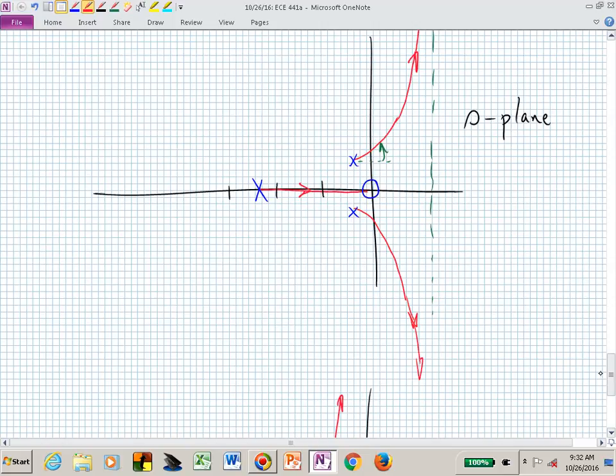So now the k, so if k is 0, where am I? If k is equal to 0, where am I in this top root locus pattern? I'm at the open loop poles, open loop in quotes, so I'm at these complex poles at minus 0.34 plus and minus j 0.56, and minus 2.3. As I increase the gain k, let's say 0.5, now this pole at minus 2.3 may have migrated to minus 1.3. The two complex poles have left and now they're moving. Maybe they're already into the right half plane with a gain of 1/2. And we would have to determine where it crossed the imaginary axis, and at what gain it crossed that imaginary axis.